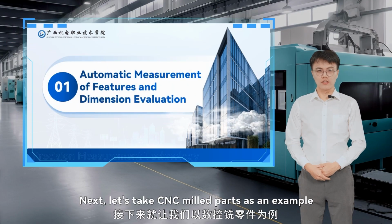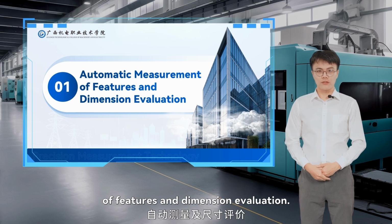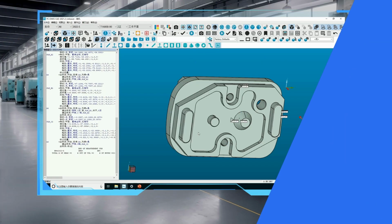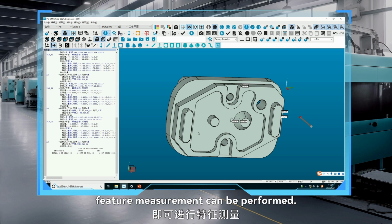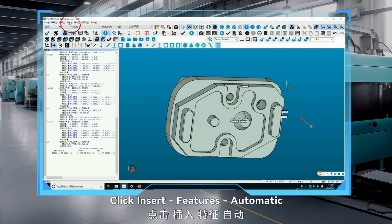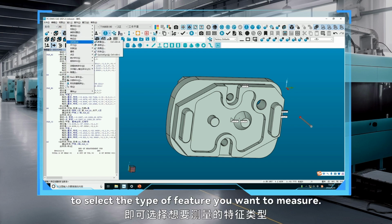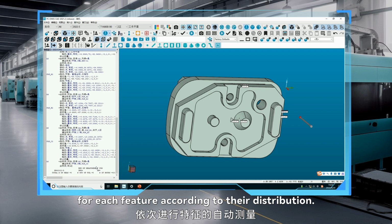Next, let's take CNC mill parts as an example to specifically learn about the automatic measurement of features and dimension evaluation. After establishing the coordinate system, feature measurement can be performed. In automatic mode, automatic measurement features are required. Click Insert, Features, Automatic to select the type of feature you want to measure. Next, let's perform automatic measurements for each feature according to their distribution.